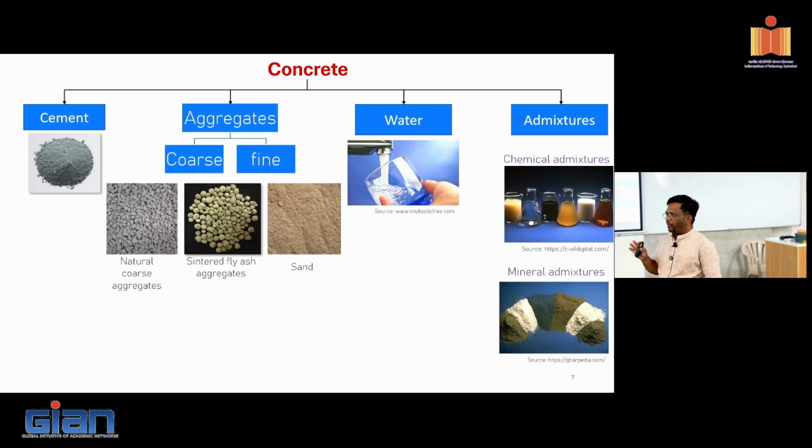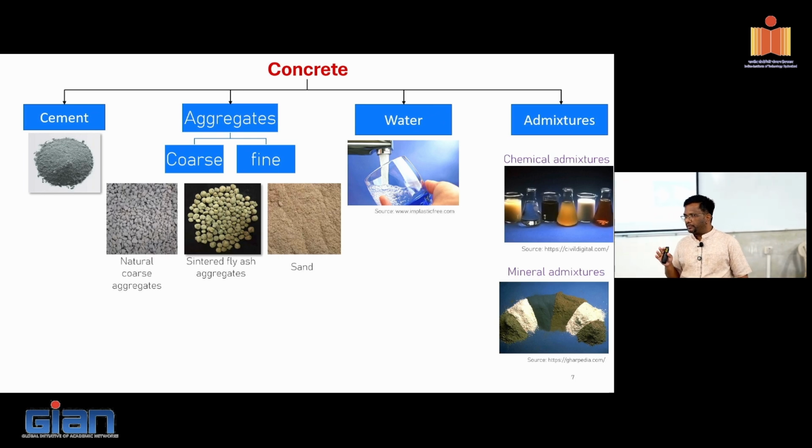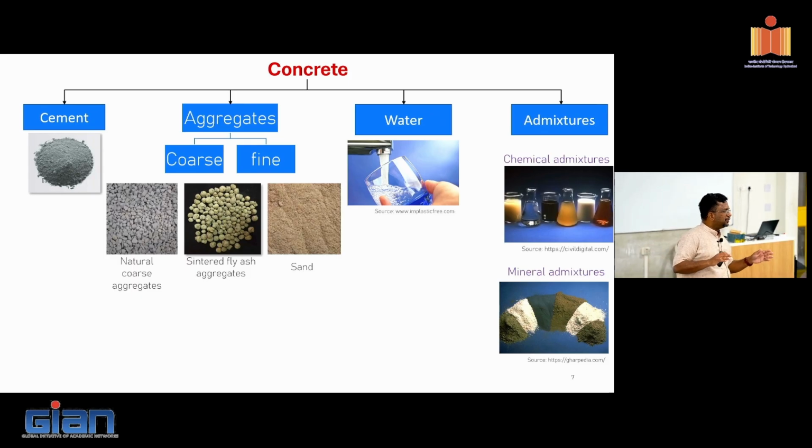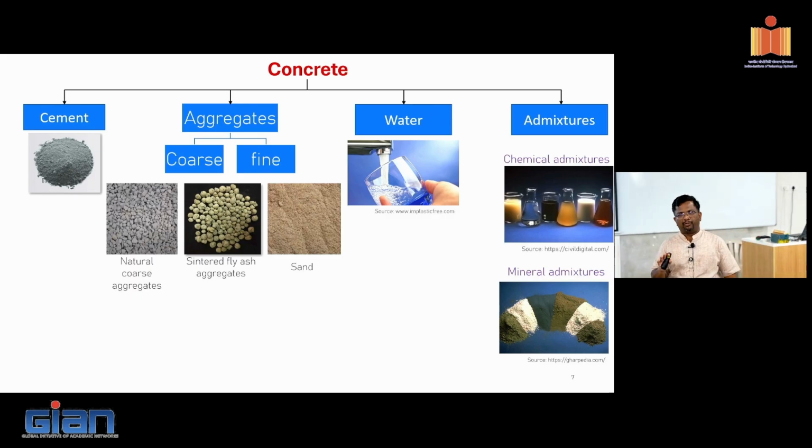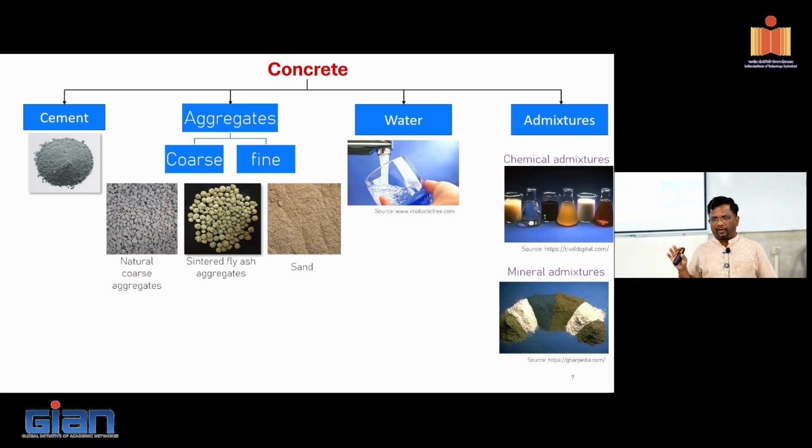So all of this, again, water. What kind of water do we need to use for concreting? pH 7. Is it only pH 7? So typically, what is it? 6.5 to 8 pH. Is that the only parameter that we need to look at? You're right. Water that is suitable for drinking is what is recommended for making concrete also. What is the other important thing that we need to be very careful about?